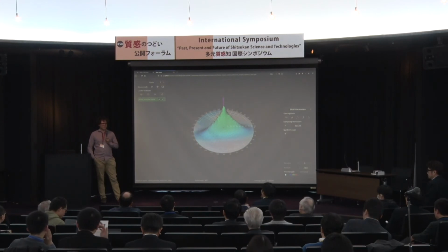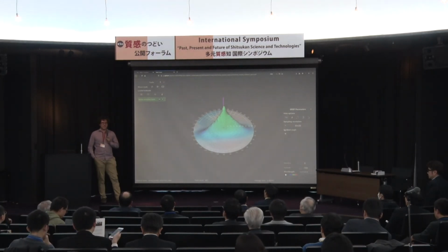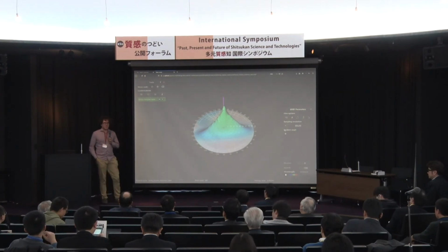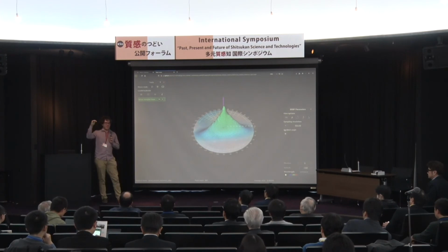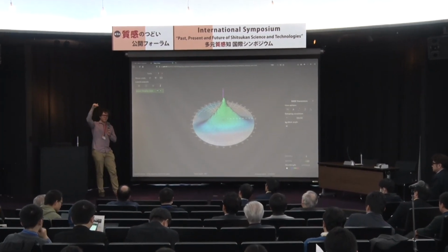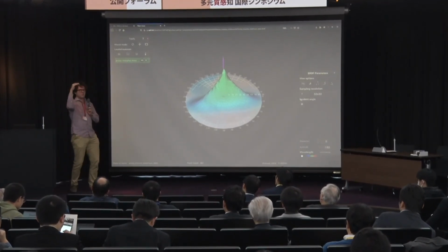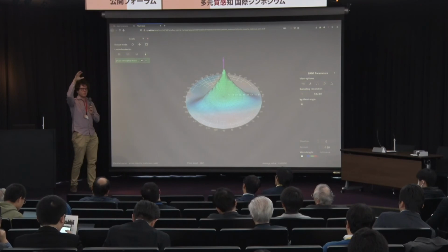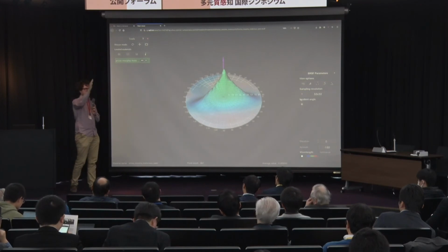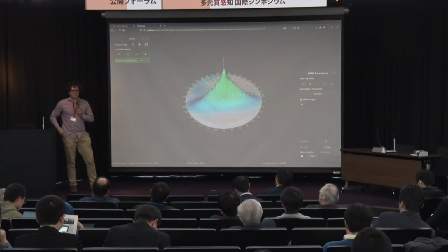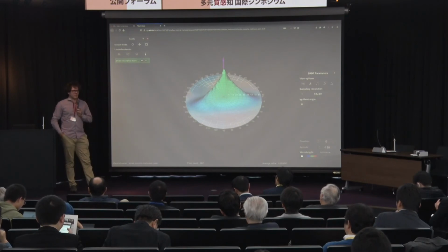Well, then it's difficult to change. Well, I guess some of these daylighting components are rather modular. So something that people sometimes do is they put these prismatic sheets on windows, and then when the sun is coming around noontime, it's almost coming down vertically. These prismatic sheets refract the light back up so that it hits the ceiling inside the room, which then gets turned into a light source, and that pushes light further into the building.